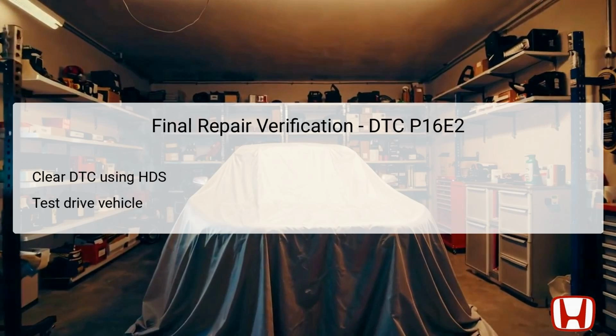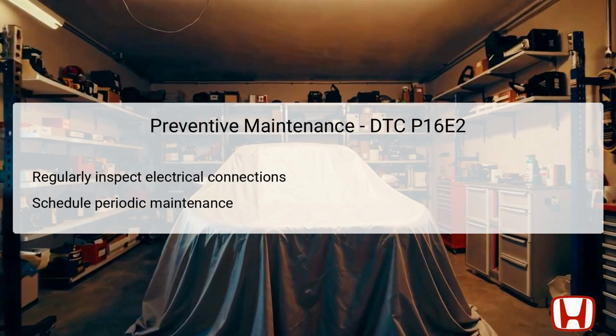However, should the DTC return, it may require a reassessment of the previous inspections and possibly further refinements in the repair strategy. Preventive maintenance plays a crucial role in avoiding DTC P16E2 in the future. Regular inspection of electrical connections, particularly at the alternator and PCM, is key to ensuring that everything remains secure and free from corrosion or wear.